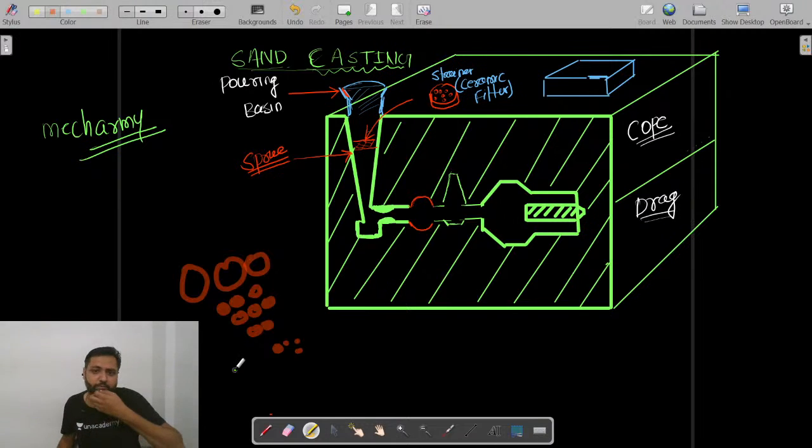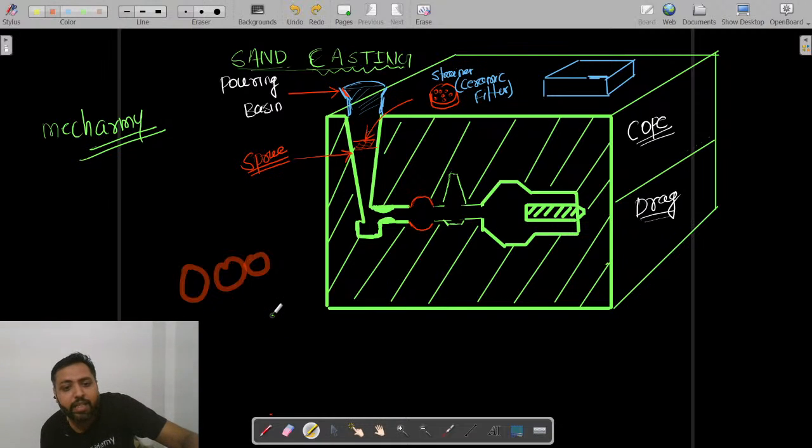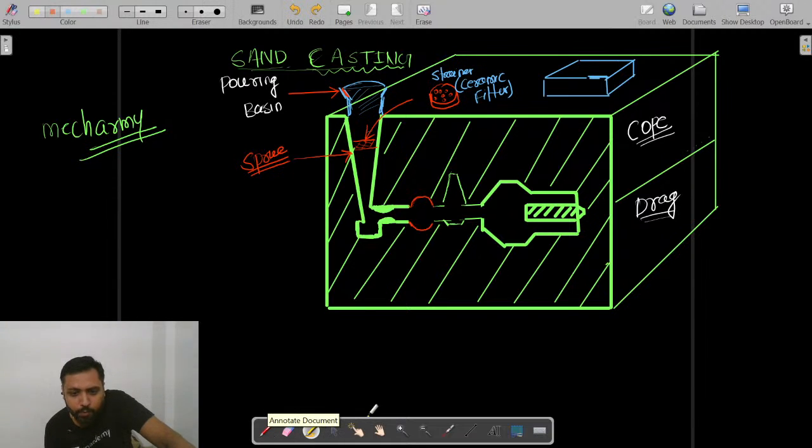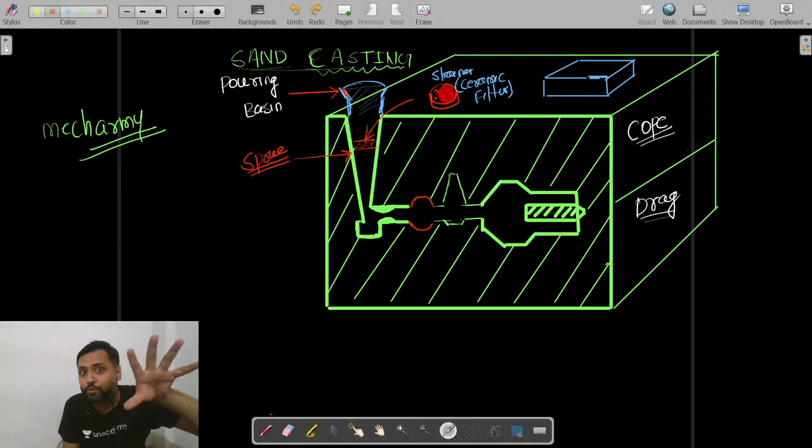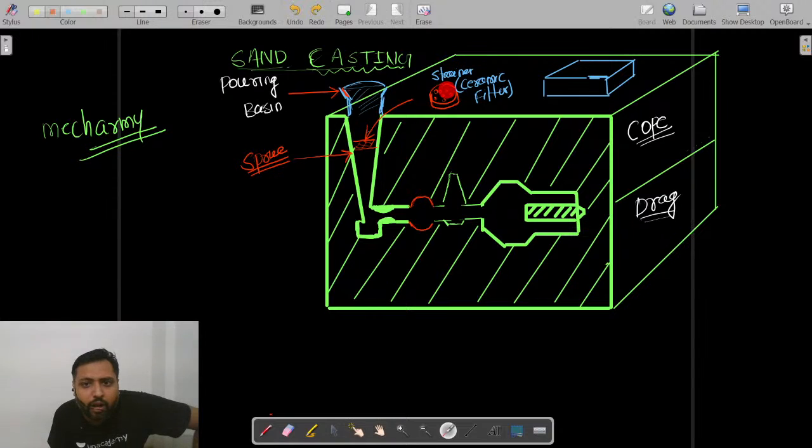Here in the first stage filtering in the sprue channel itself, you place a strainer, which is like a carom board coin having small holes, not large holes. Yes, it has small holes, but this small hole cannot be too small so that it filters very small impurities.